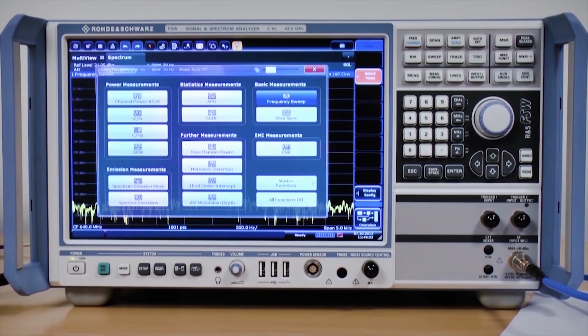Spectrum analyzers rely heavily these days on processing technology. They often contain many inbuilt routines. These cover many functions, everything from channel power to harmonic distortion, third-order intercept and AM modulation measurements. Two routines that deserve special mention are phase noise and spectral emission mask.